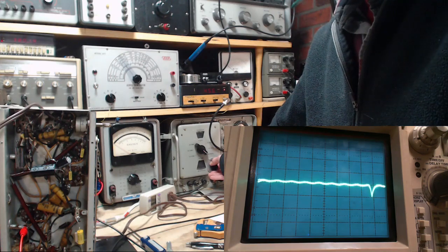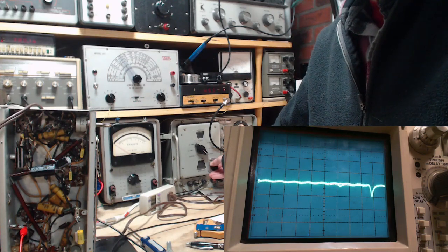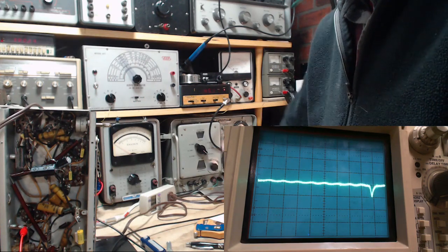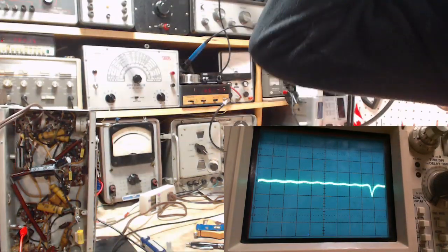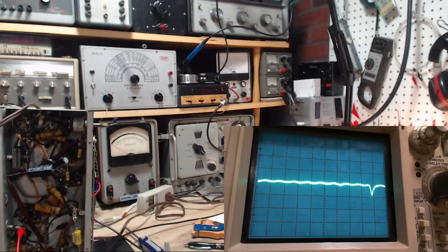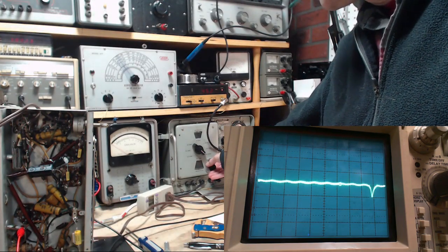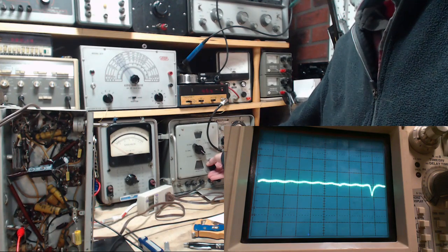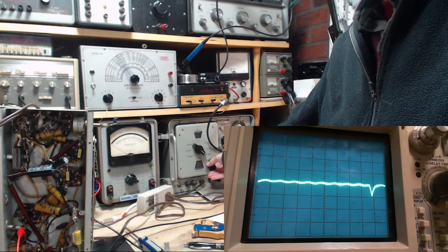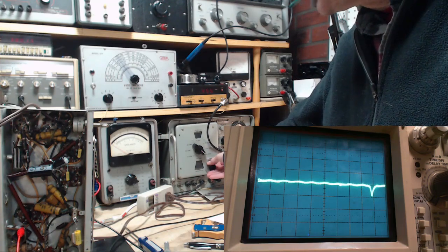Far be it for me to explain how this is doing what it's doing right now, but it's doing something. So I've now got the signal generator right on top of this curious point. And what does it say? 451. And if I put it up to 4, so that would be 455 right there. So that's what we're seeing there. We're seeing the IF.